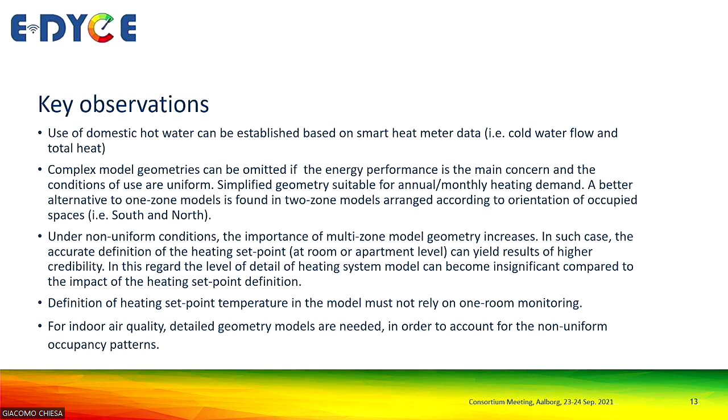The complex geometry models, when we are trying to simulate the heating demand, at least for the Danish cases, can be omitted if we are only interested in the heating demand in general terms, on longer periods such as a month, for example, or a year. However, if we are looking at shorter periods, such as weekly data, or want to know about the activation of the heating system, then a little bit more advanced models would be advised.